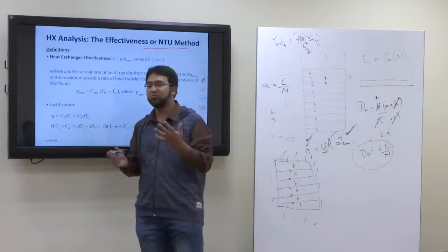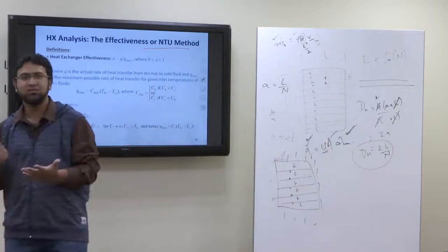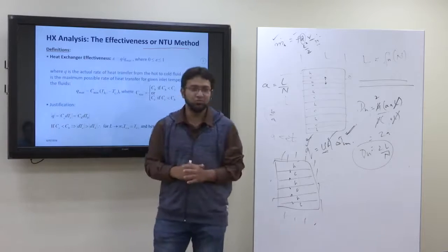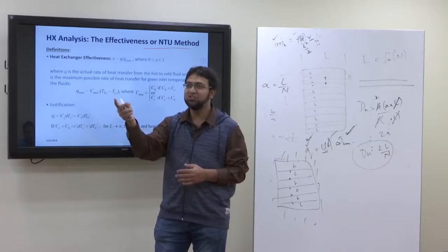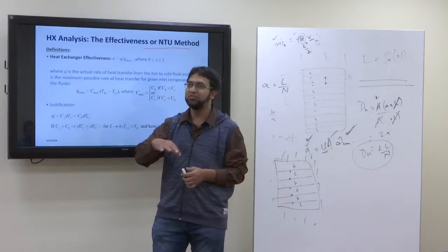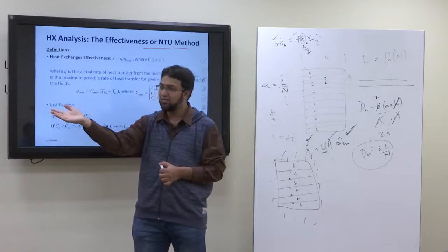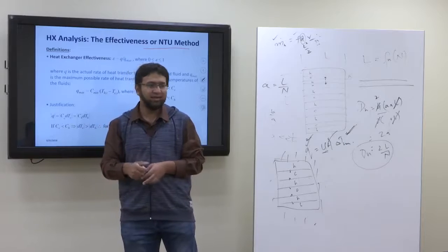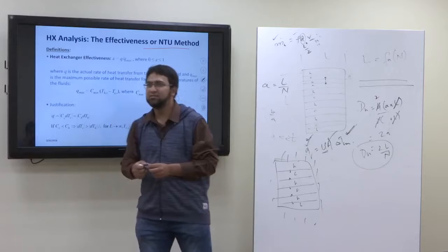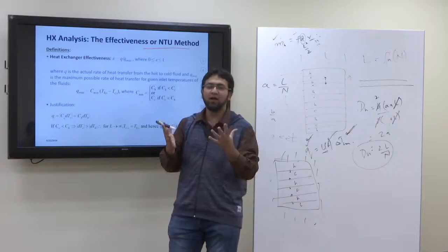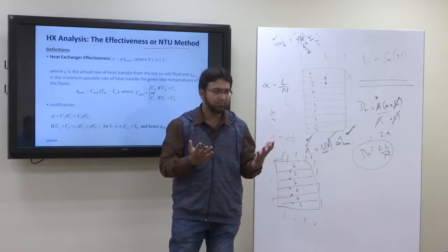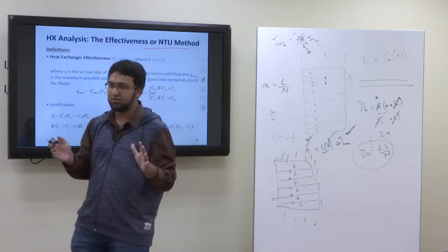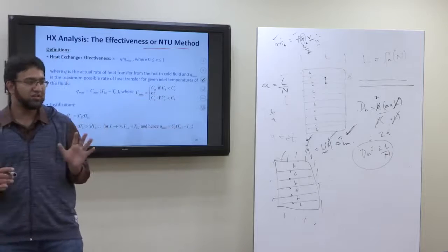But how are you going to define the efficiency of a heat exchanger? What is outlet? What is inlet? The main thing is the heat exchange which is going through. The outlet of heat exchange, suppose the hot fluid is providing heat, will be the same as the amount of heat collected by the cold fluid. So heat exchanger efficiency is not an appropriate term to define how well the heat exchanger is performing. That's why we don't define efficiency of a heat exchanger.